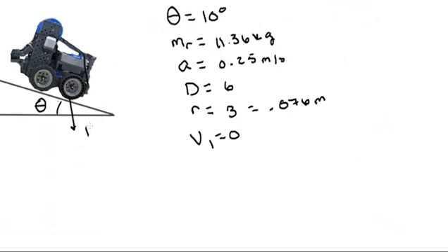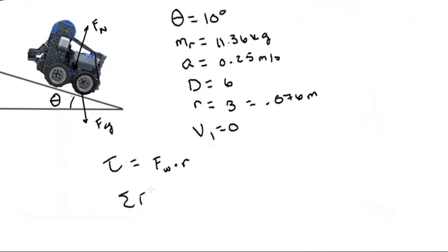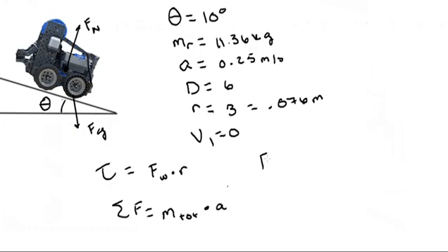The vertical forces that act on the robot are the force due to gravity and the normal force, which is the upward force on the wheel. Since the wheel is rotating, the torque of the wheel will be represented as the product of the force of the wheel and the radius, which is 3 inches long. In this case, the sum of the forces acting on the robot will equal the total mass multiplied by the acceleration. In order to figure out the formula for force, we'll designate if the forces are positive or negative.